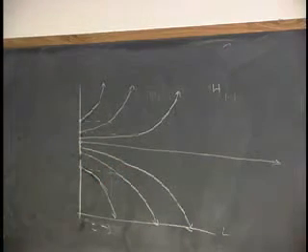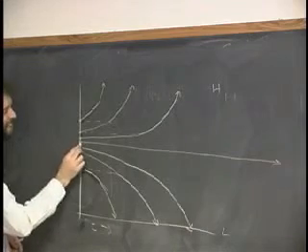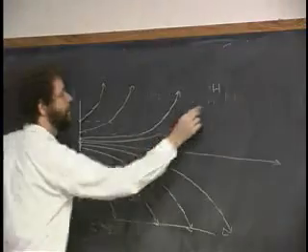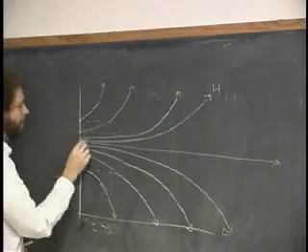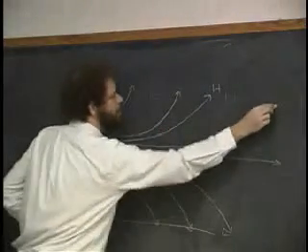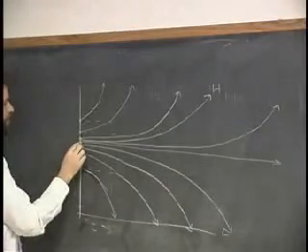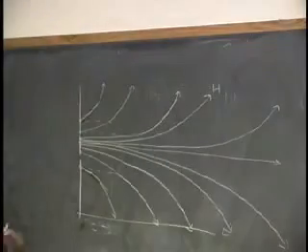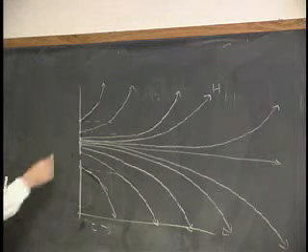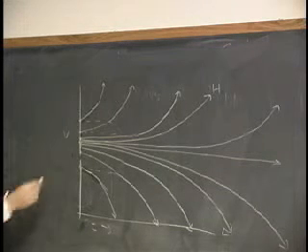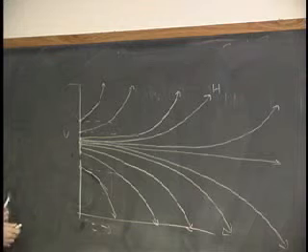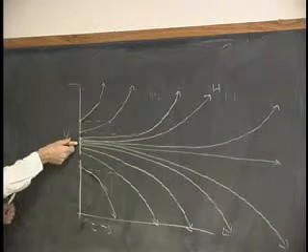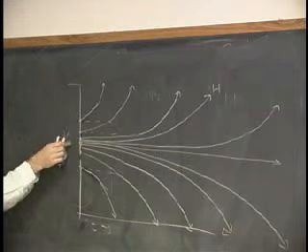Okay? And then if we're half of that, now I'll start to get a little loose here. Now I draw. That'll go like that, and then even closer, a curve perhaps like this. What are your axes? So the x-axis is time, and the y-axis could be anything. Let's say that it's voltage, V, between a high voltage and a low voltage. And in the middle is the balance point, the metastable point. So here we're looking at how we evolve with time.